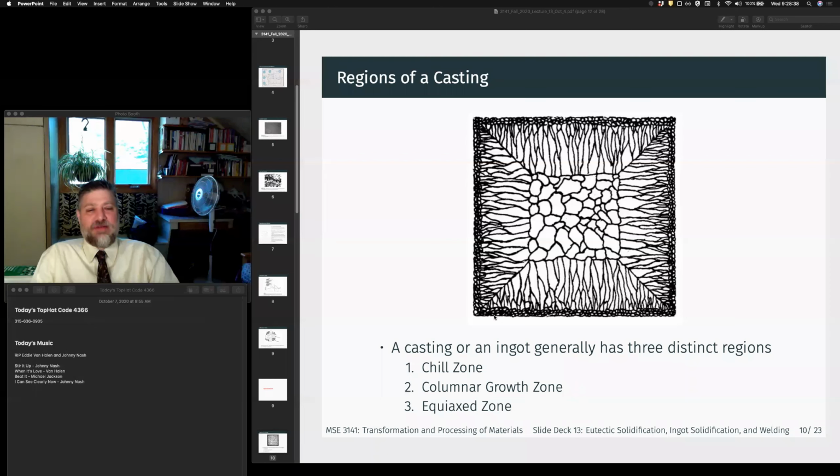Energy cost is always a safe guess, but in this case, it's not. As it cools, it goes into a different phase region? No, you get this even if it's a single phase. Well, okay. The equiaxed region is dendrite arms breaking off and nucleating new grains. I have to be careful about what I say about this columnar region, because if this was a pure metal, it would be different than an engineering alloy, right? You wouldn't get as pronounced of a columnar structure unless you had thermal dendrites.